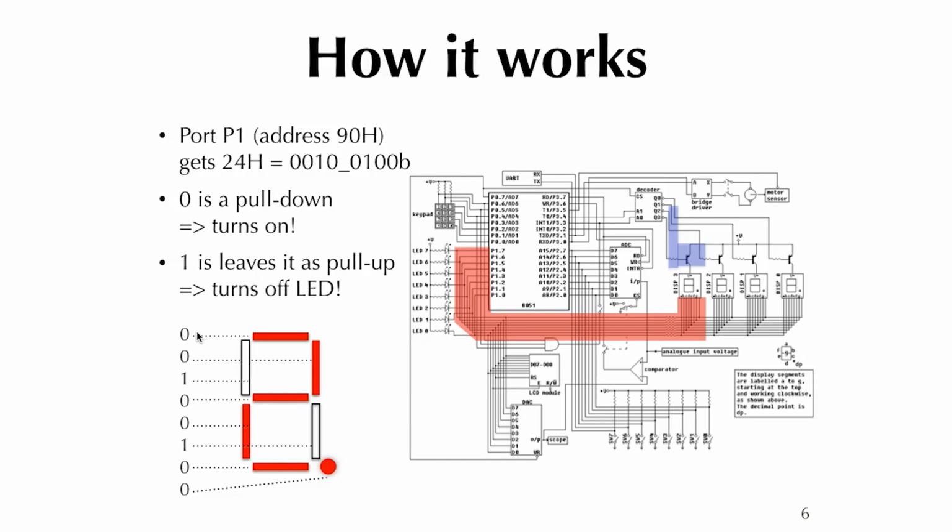Because an LED is something that needs power. It's not just a logic value. GPIO or these pins are supposed to indicate a logic value. So they may go from 0 to a high value, but they don't have a lot of current. Even though they can have a high voltage, if you don't have enough current, that's not enough to turn on a light. So you don't want to use the microcontroller as your power supply for the LED.